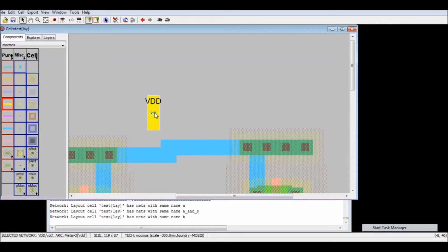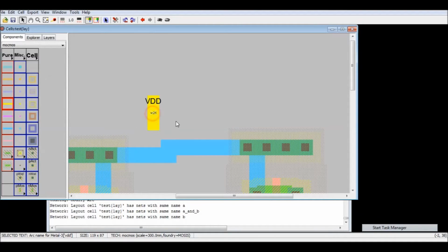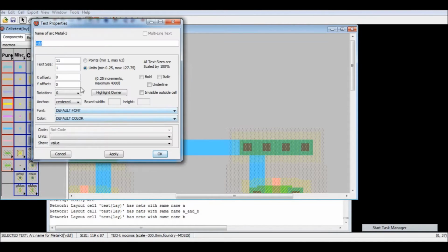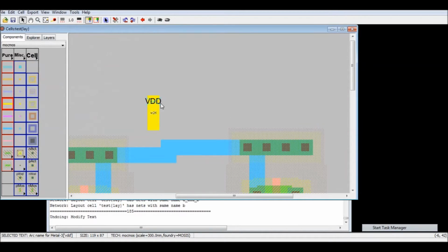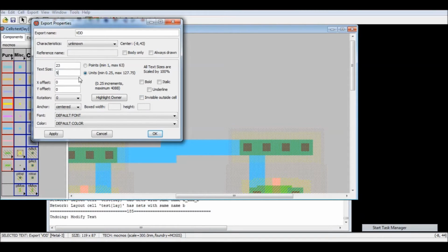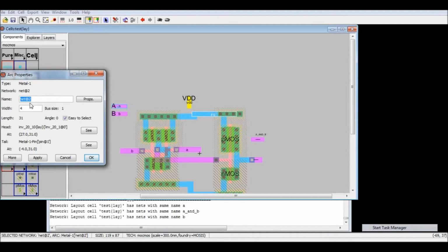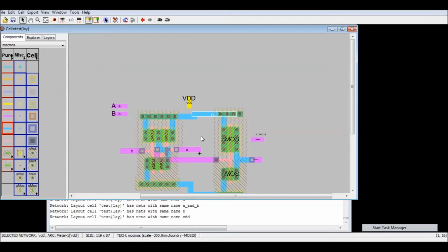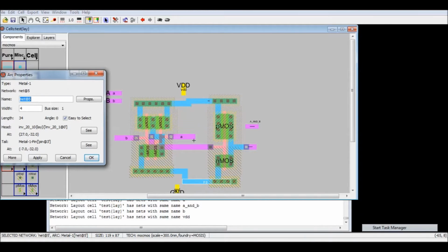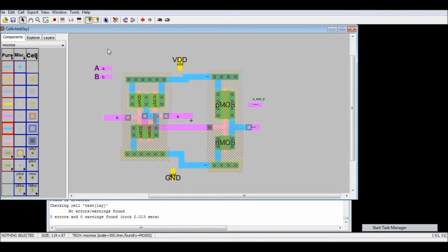Yeah, I think. Okay. Make it 5? No. I think I was yeah, this is. This should be 5. Okay, cool. Now the last step is that we need to name this net. This is VDD. Just any one of them will suffice. And this is GND. Just to tell the simulator where to connect each part. Okay, so this concludes the design of the AND gate.